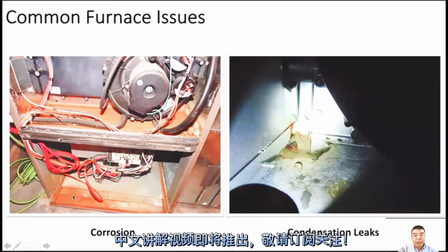If they didn't have maintenance, the water just drips from inside the furnace and causes the same trouble. So this one looks like not a leak from the furnace, but from the humidifier or possibly the A coil.